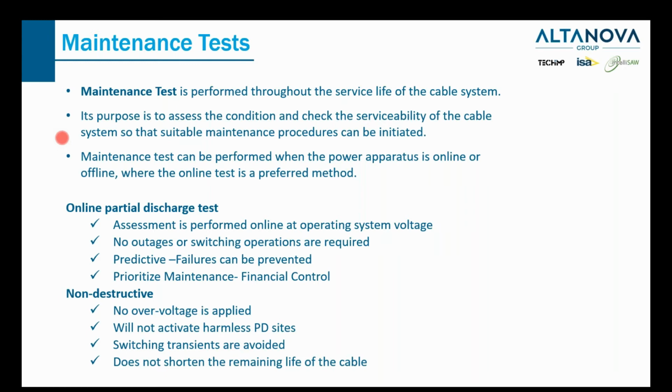Also, online test is a real non-destructive test, and there's no overvoltage at all. The equipment under test is operating in its normal condition, and because there's no overvoltage applied, the online test will not activate any dormant PD sites.